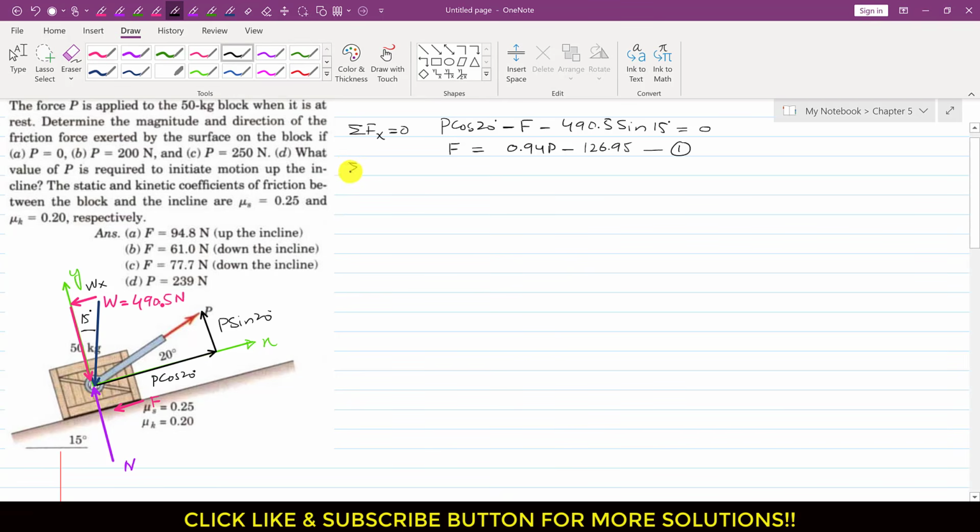Now if I apply the summation of forces along y equals to 0, the normal force is acting in the positive y direction, so I will write N. Then the cos component of this weight is acting in the negative y direction, so I will write minus 490.5 cos of 15 degrees, and similarly this component is acting in the positive y direction, so I will write plus P sine of 20 degrees, and this is equal to 0.